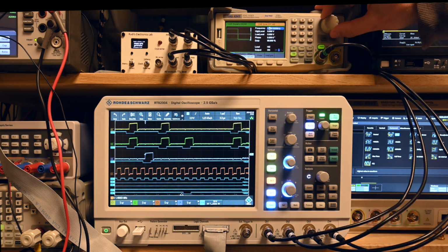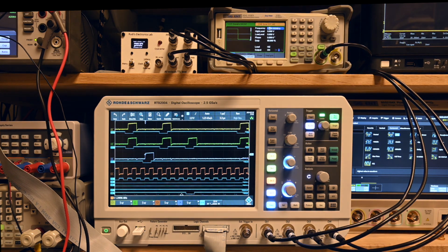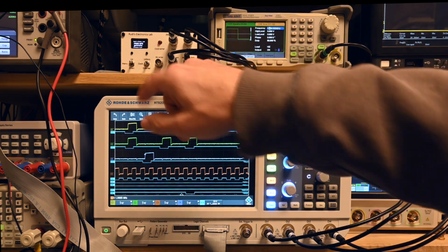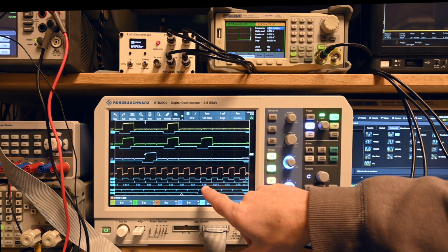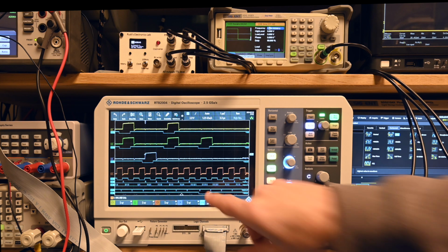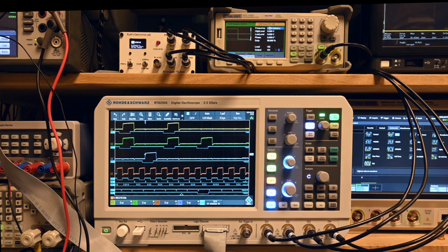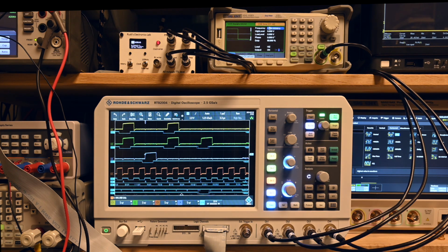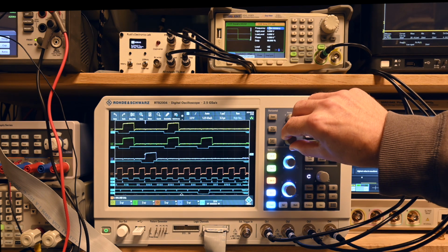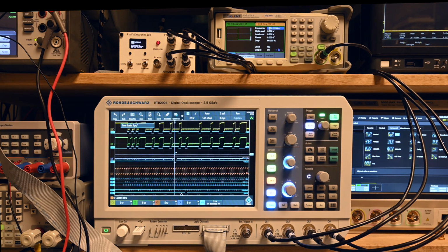What is the reason why the device is faster in regular mode than in debug mode? Well, the thing is, and I'm bringing you back to the debug mode here, in order to run the debug mode, you have to use a write pin on the Arduino several times. And the write pin takes quite a bit of time, and that makes the algorithm a little bit slower. And so in order to be able to see this information externally, you have to go to a slower algorithm, and so the maximum speed is slower. But anyway, altogether the device seems to be doing exactly what it needs to do.